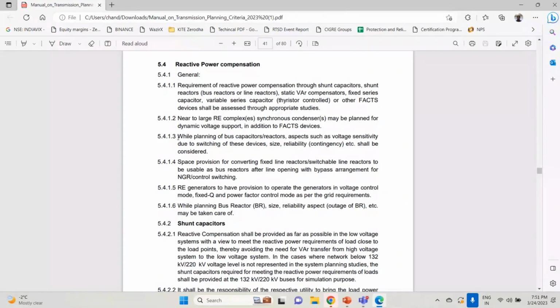But here you extract energy from a motor or something like that, so that you can rotate the rotor itself and absorb reactive power from the system. So it is not going to generate any active power. It is only going to absorb or generate reactive power in the system. However, you can further put a flywheel to provide inertial support. This is what we mean by synchronous condenser.